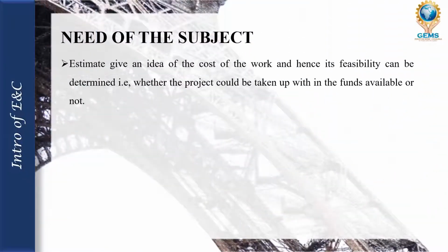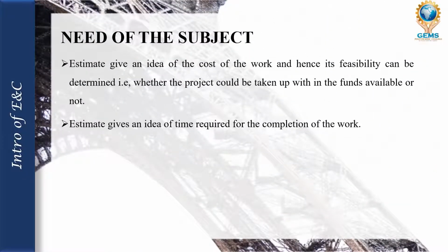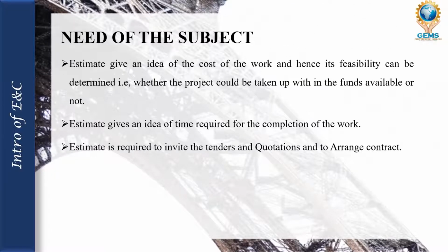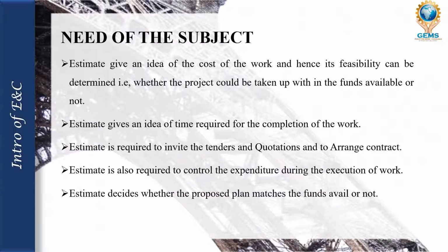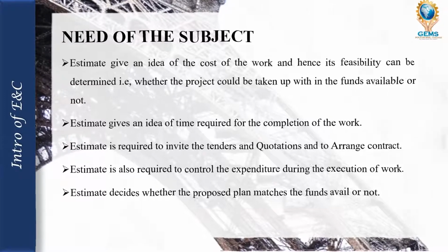Then what is the need of the subject? An estimate gives an idea of the cost of the work. An estimate gives an idea of time. An estimate is required to invite tenders. An estimate is also required to control the expenditure, meaning how much amount we are spending on the project. An estimate also decides whether the proposed plan matches the funds available or not.